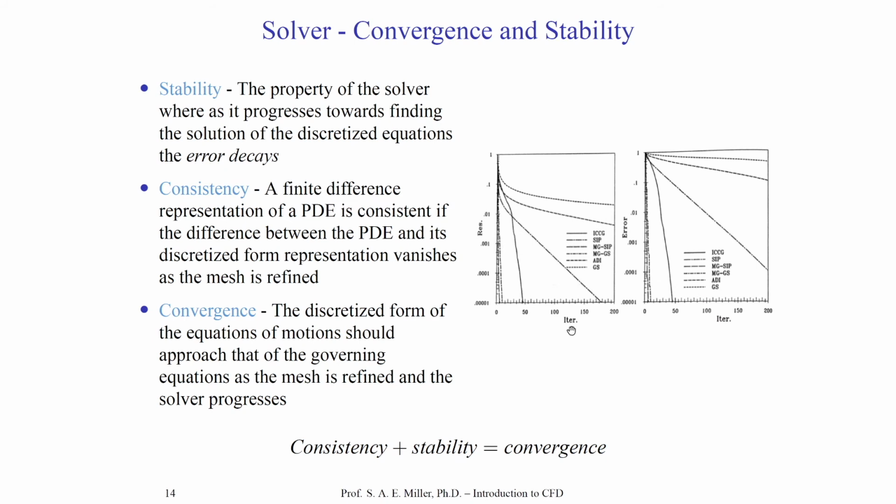On the figure here on the right, you see an x-axis, which is iteration, and a y-axis of residual. Residual is a type of error estimate, which we'll talk about later. The other y-axis is the error, which is, of course, the difference between the discretized solution and the analytical solution. On the x-axis is iteration. So this means for higher iterations, the solver has approached and is trying to estimate a more accurate solution in terms of reducing the error and comparing it to the analytical solution.